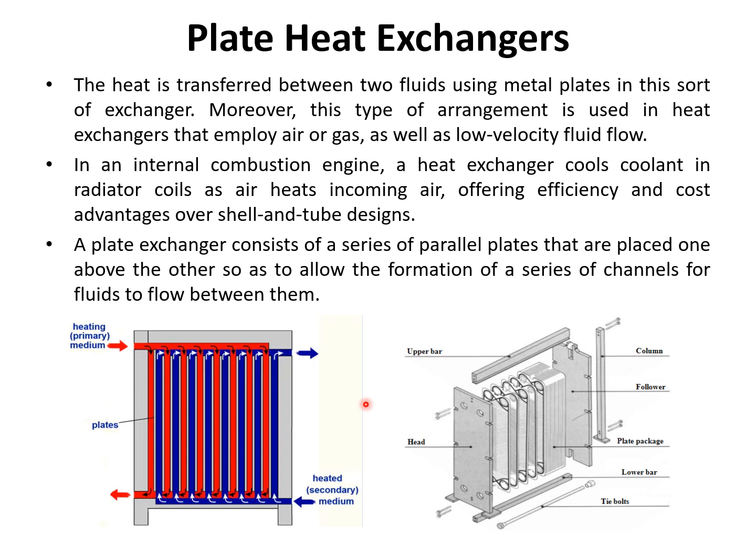And the medium has to be very clean, in the sense that it should not have any contamination. Otherwise, every week or month you have to open these plates and clean them. So you use a plate type heat exchanger only when your medium is very clean and you have very little space, where you don't have much room to put a tubular exchanger. Be sure to use this type of exchanger with a clean medium.